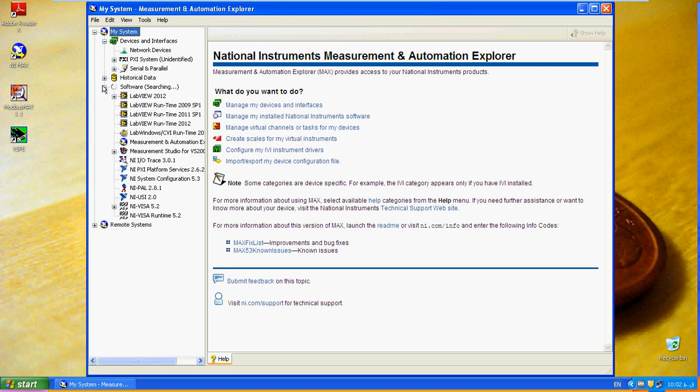The software components include the core component of LabVIEW. Here it is LabVIEW 2012. NI VISA 5.2 is already installed. NI VISA is needed. Also, the Datalogging and Supervisory Control module should be installed on the system. So there are 3 requirements: the core component of LabVIEW 2012, NI VISA for the serial communication, and the Datalogging and Supervisory Control module to understand the Modbus protocol.